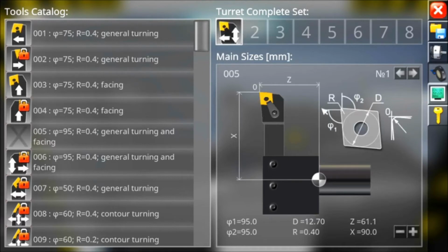What also matters when I'm going to mount a tool is the protrusion. The tool must always protrude as little as possible, taking into account the overall dimensions of the machine. The more it protrudes, the more I run into possible vibrations. If it is a boring bar, I will have measurements that are not constant over time, with a roughness that is too high compared to that required. Let's make it protrude as little as possible.